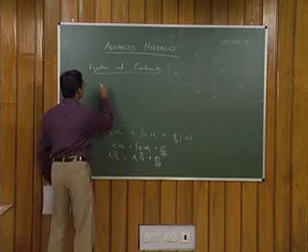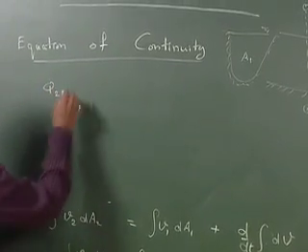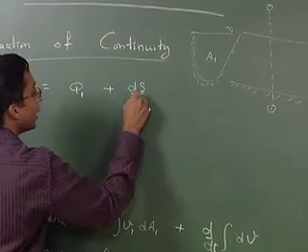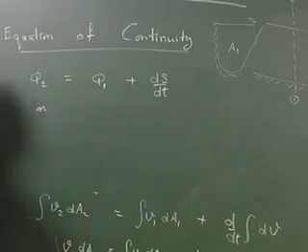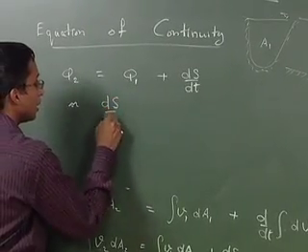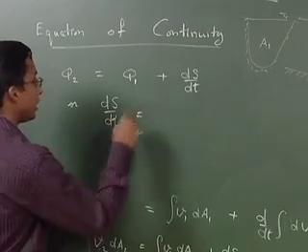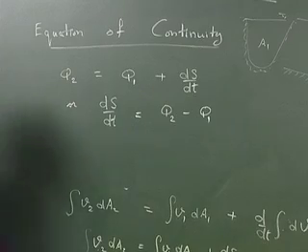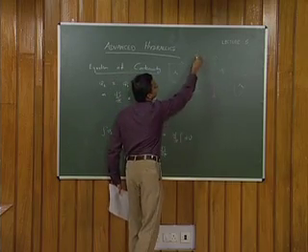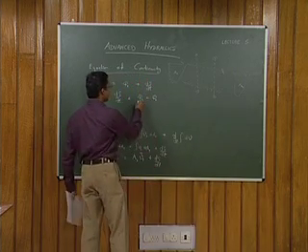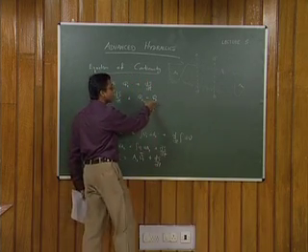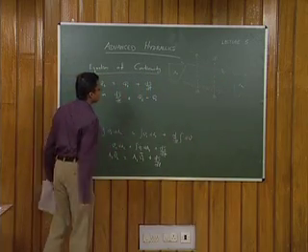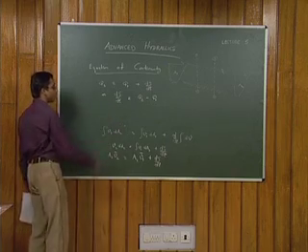Subsequently, you know that this is the quantity discharge, Q2 is equal to Q1 plus dS by dt, or the more familiar expression is change in storage dS by dt is equal to Q2 minus Q1. So, that is the change in storage between two sections 1 and 2 is nothing but equal to the change in discharge between the two sections. That is how an incompressible fluid flow in an open channel can be described.